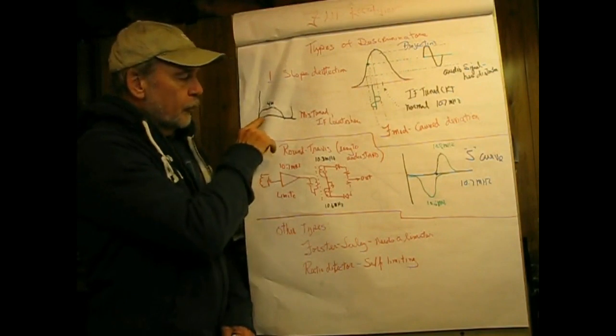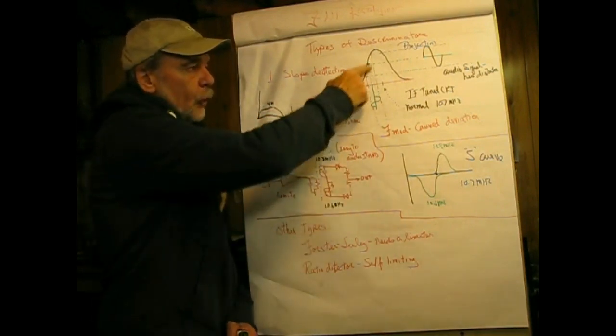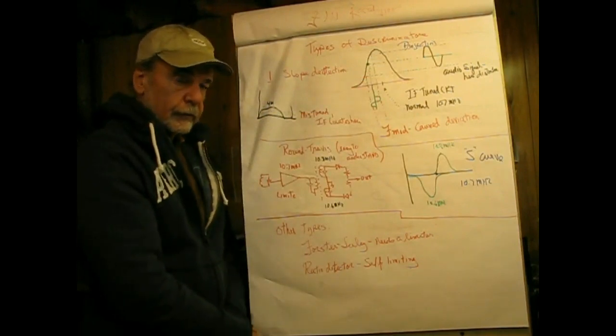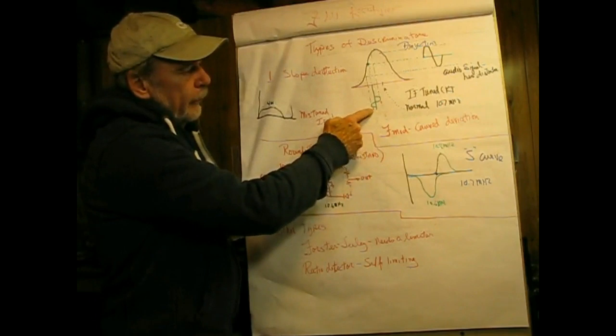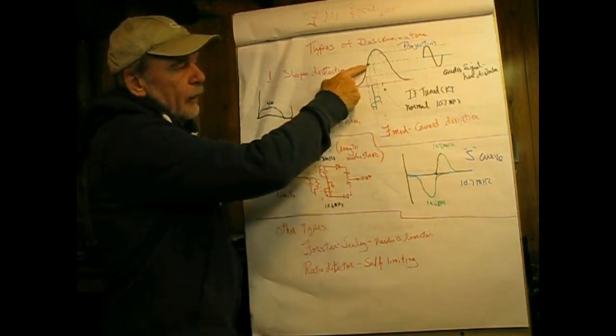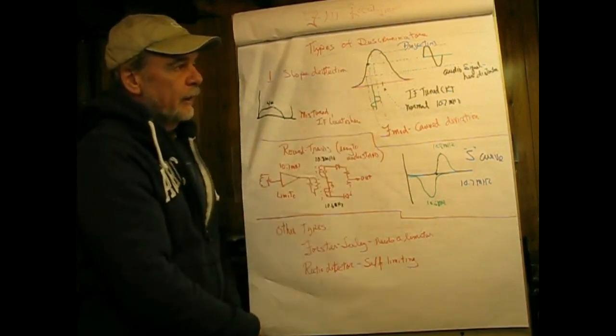amplifiers. Now it's broader like this, and I've just shown it like this here for the sake of ease. And by mistuning it, the intermediate frequency locates on the slope of the response curve of the IF.